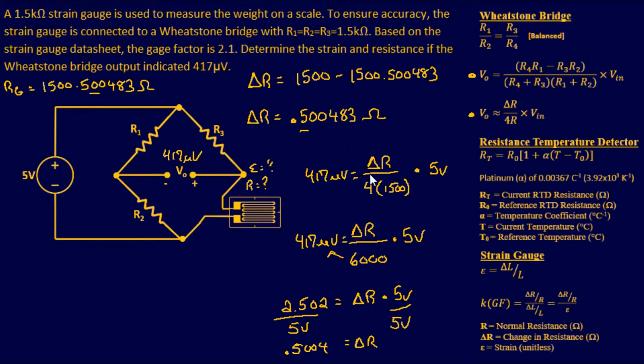So that's a good sign, because right there, that looks like our difference. Now again, the reason it's about is because see how accurate I was able to go with using the big equation? So just keep that in mind. It's not perfect, but it's pretty close. Well, so now that I have the difference of resistance, now I can easily find my strain. And by doing that, I can use this equation right here. I'll tell you what, I'll see if I can finish it off down here.